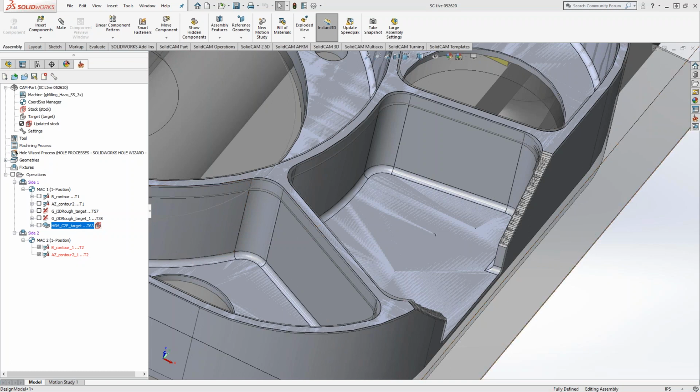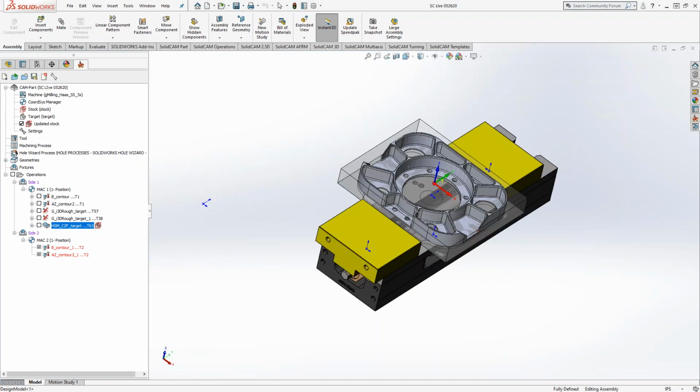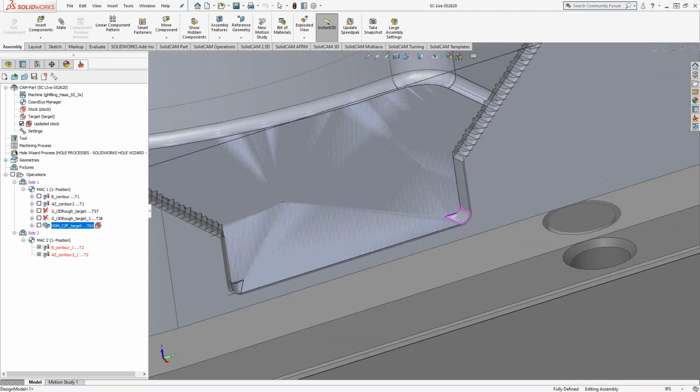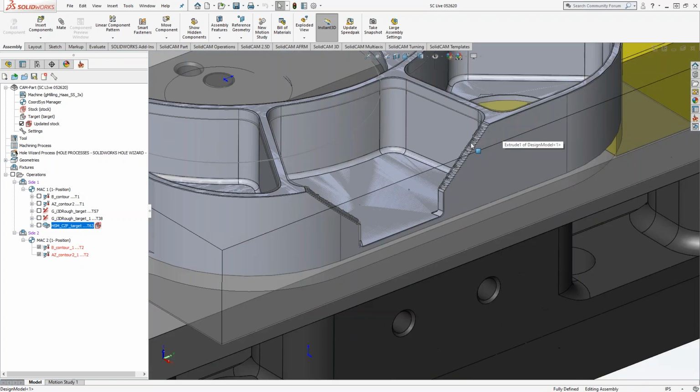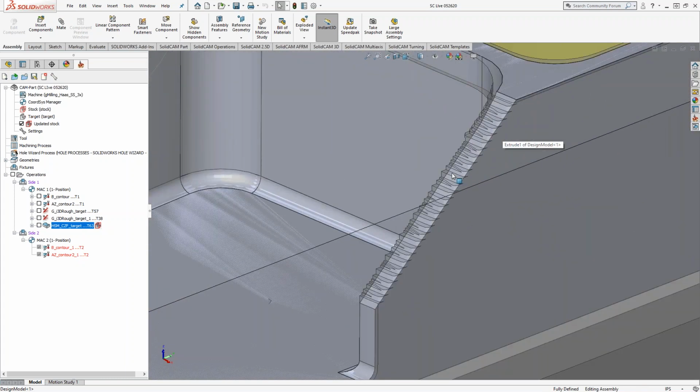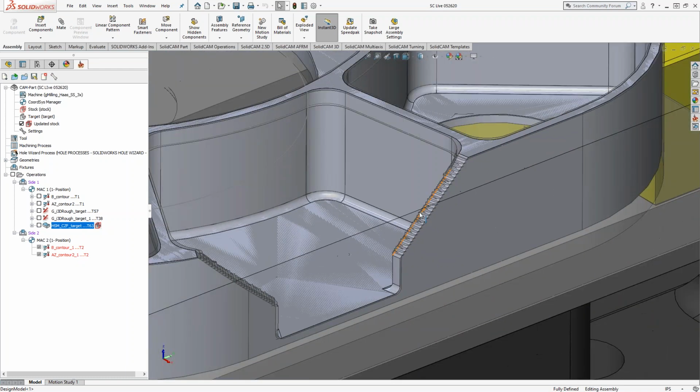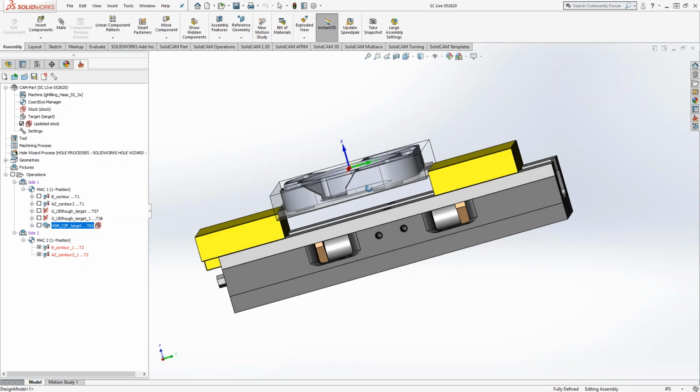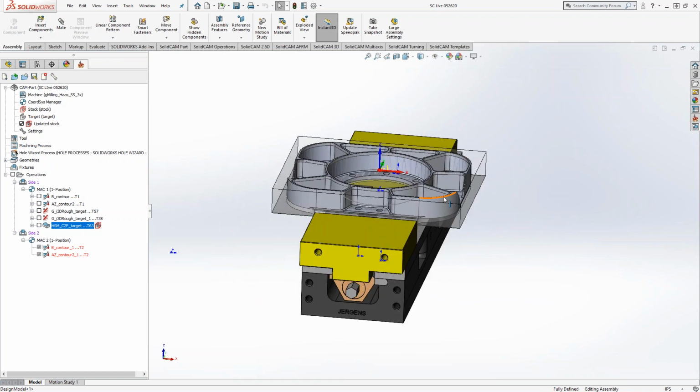Now all we have really left is our drilled holes as well as our taper that Mark is showing right there. So really neat. We got a pretty decent part here with a lot of cavities, a lot of holes, and we were basically able to do this, I would say 90% of it, within 2 or 3 operations since we're using multi-tool. Yep.